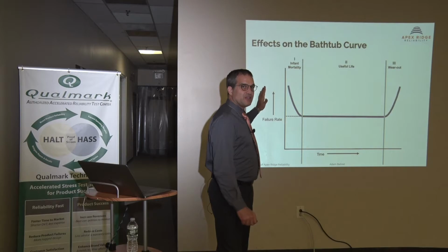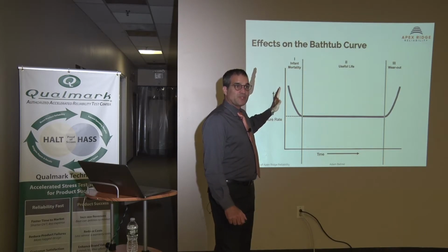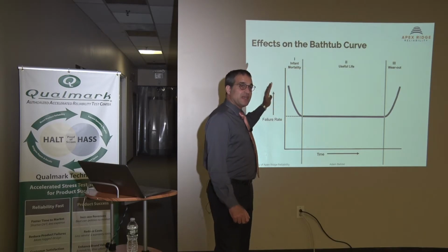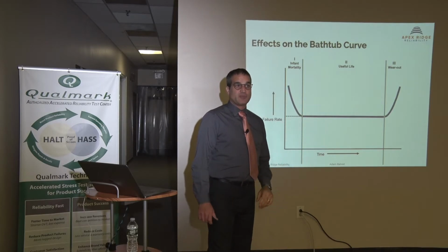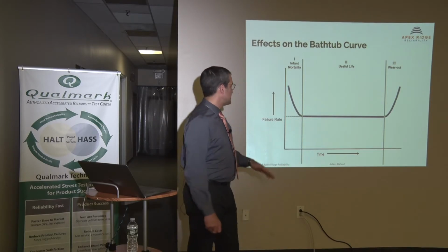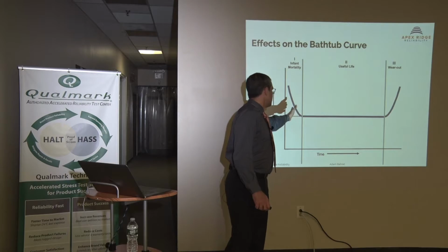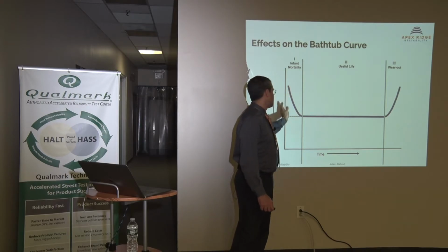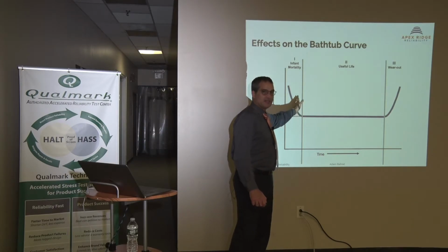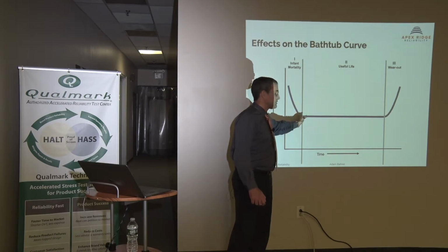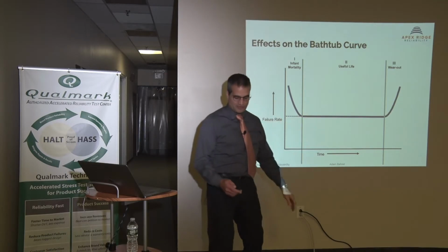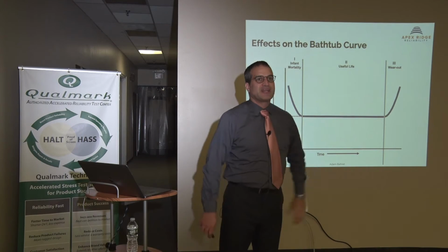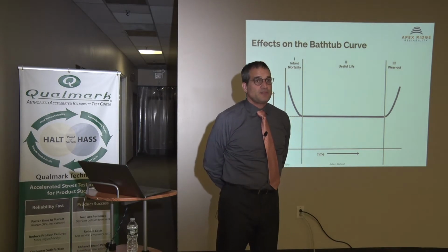But it's saying that you have a lot of infant mortality, right, with quality defects, and that those quickly are exposed and removed from the population. So ideally, this is from the first time you turn it on, so you do your burn-in and your HAS testing to here, and then give it to the customer, hopefully around here is when it's released. And then you hope for a somewhat constant failure rate for a lot of its life.